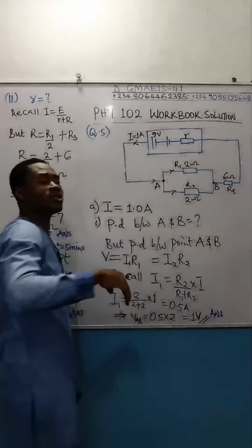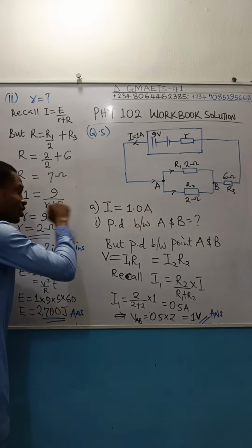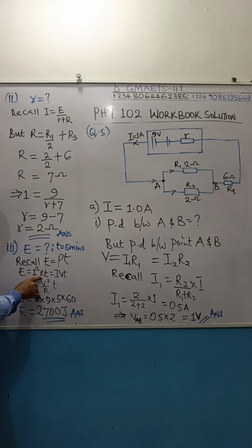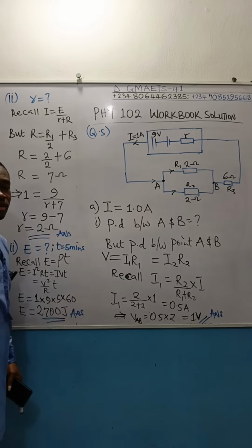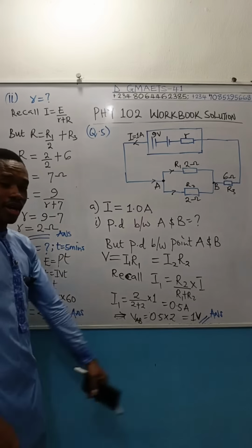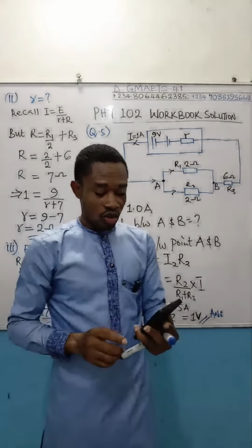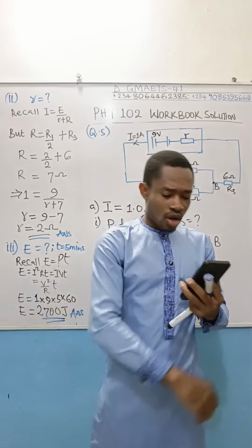All of them oppose current here. So the formula for this circuit is meant to be I squared times R plus r, that is internal resistance plus external resistance, times T. You have to add both of them. So you get that 9 there, and then you multiply by that value to get what the correct answer should be. All right, so that is that.